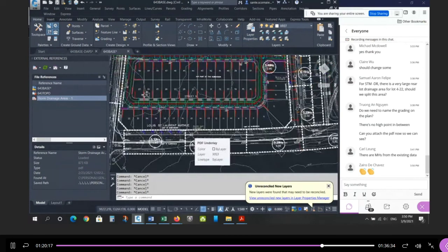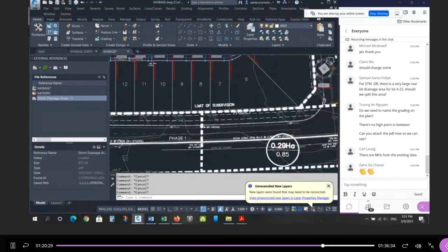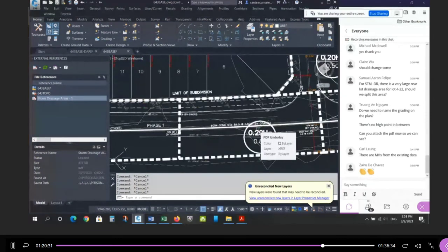Again, the image really slows down the drawing. There's a lot of data there. It's actually a PDF, but it's got vector data in it. That's why you can snap to endpoints, and sometimes even if it's really smart, you can actually snap to the center of stuff. So some of the O-snaps work, some don't. Depends on how the geometry comes through on the PDF.